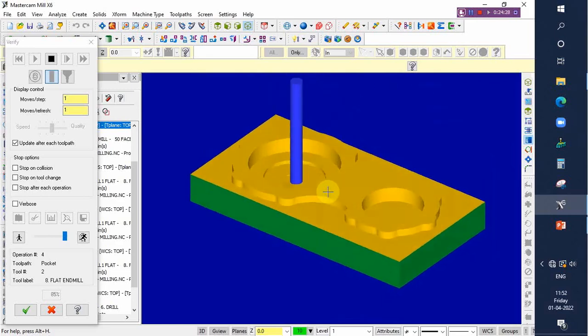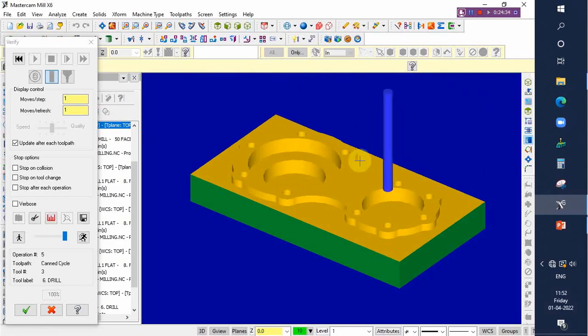Facing completed, side milling operation completed, nothing but a contour milling, 2 pocketings left side and 1 pocketing right side. All the drilling operations are carried out. So this is the way to do the milling operation by using the Mastercam software. And then how to generate the coding, so that is very, very important.